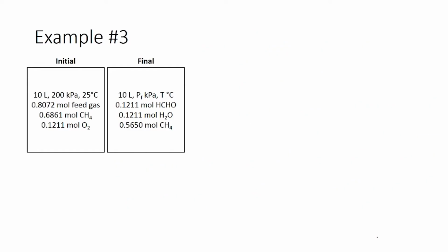To calculate the change in internal energy delta U, we need the internal energy of the reaction as well. So, delta U would actually be equal to sigma of n final times U cap final minus sigma of n initial times U cap initial plus xi, which is the extent of reaction, times delta U r, which would be the internal energy of reaction.